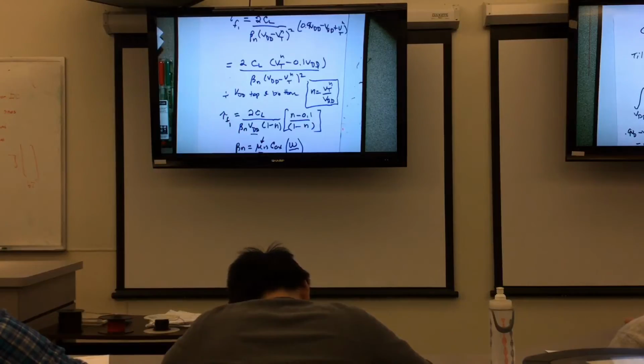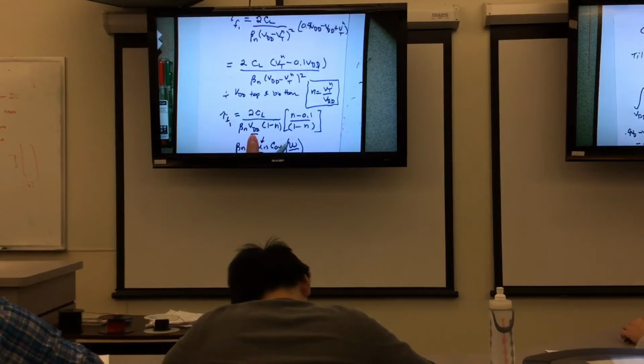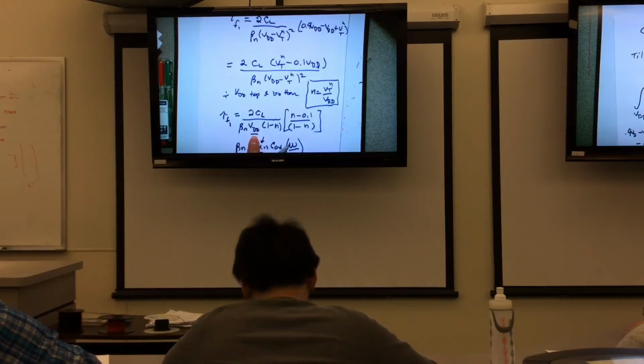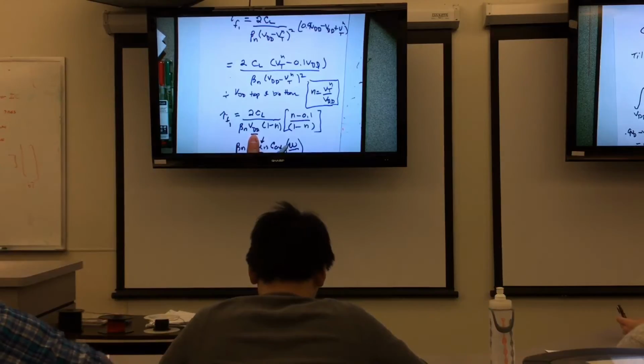But the energy stored on the final capacitance would be higher by the square of VDD. And that used to be the rule. If you wanted a high frequency microprocessor, you had to run towards the high end of VDD. Most of the higher clock rate processors that IBM makes now, the z196 at 5.5 gigahertz without using liquid nitrogen, you do have to have maybe 1.2 volts. So it's on the high end of VDD for today's types of transistors.